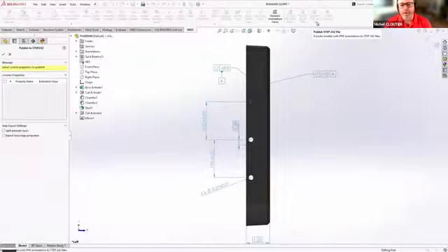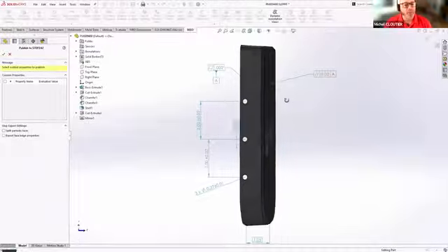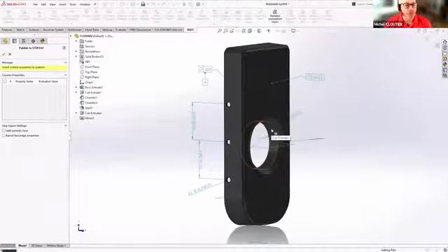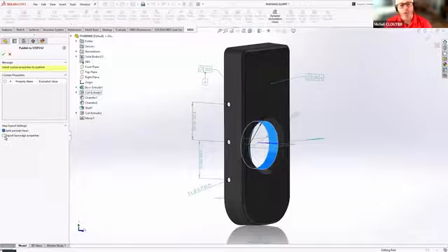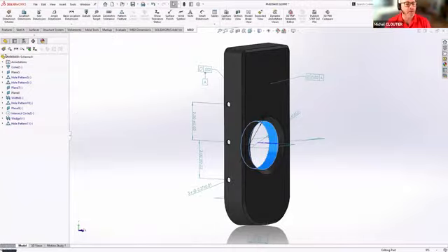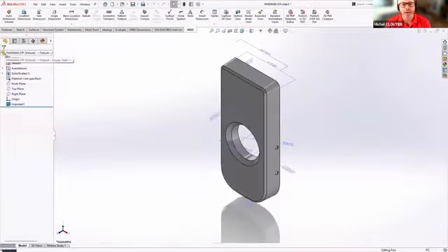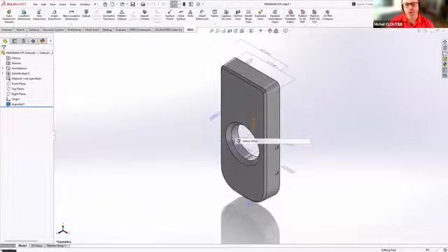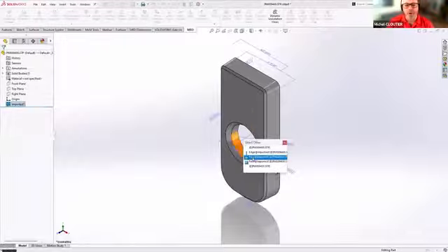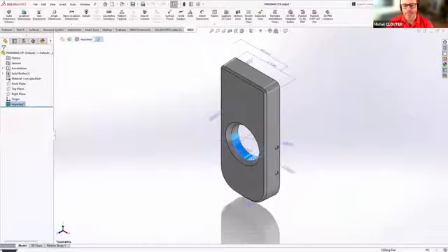And the last thing I want to talk about is the ability to export in STEP 242. So using SOLIDWORKS MBD, it does give us the ability to export in STEP 242, but we have more controlled information or options to split periodic faces or export the face edge properties into my STEP 242. So downstream applications that are going to read that STEP 242 have better information with the STEP file.